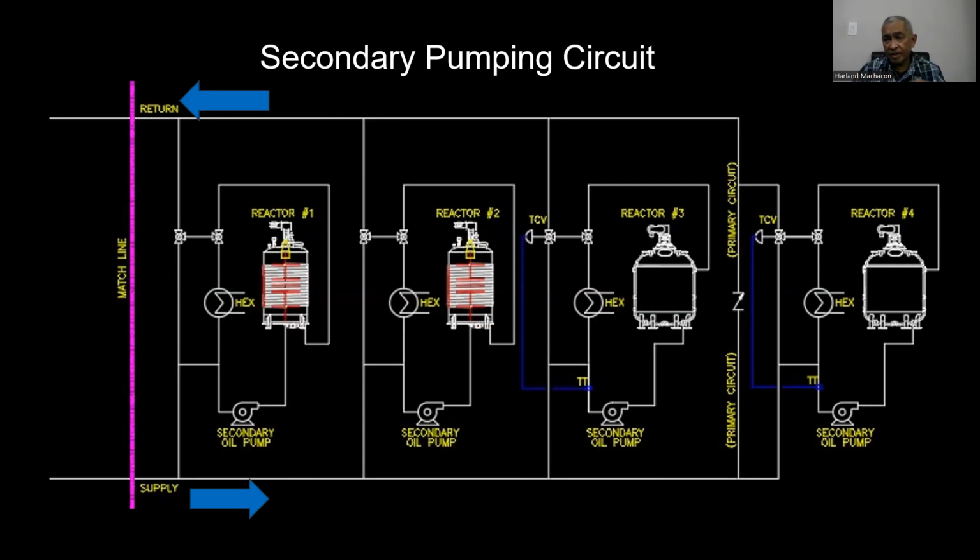And once we have a reaction being started, and it is exothermic, we need to maintain the temperature. So how is it being done? The cooled oil here is cooled further on the heat exchanger with water coming from the cooling tower to reduce its temperature.